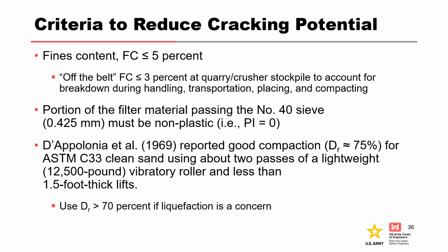Compaction of filters should be minimal. Very densely compacted sands can result in overly brittle zones that have less than desirable self-healing properties. Excessive compaction, particularly of crushed rock, can lead to the creation of sufficient fines in the filter to make them susceptible to cracking. Dynamic loading by the compactor is the critical component in compacting granular materials.